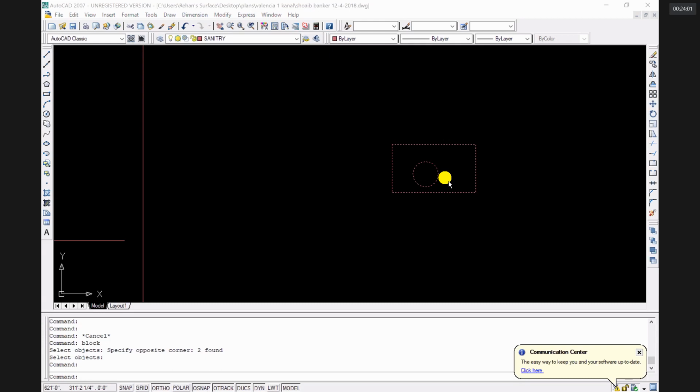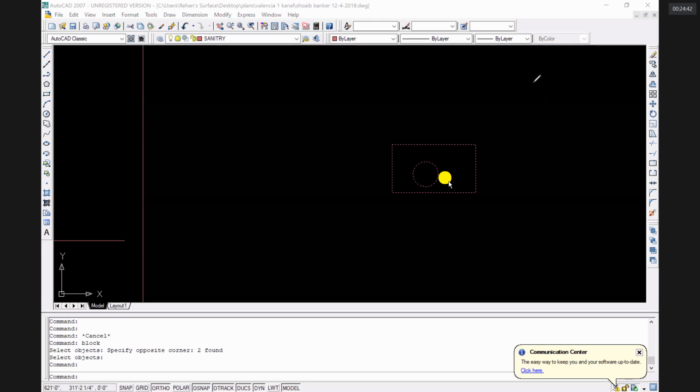Now, if any foundation is constructed at the property limit, your foundation cannot go outside that line. So what is done in that case? Unsymmetrical or asymmetrical foundations are provided. It means whatever steps you are extending on both sides would be extended on one side only. I can share a sample of an unsymmetrical foundation with you, but I would also draw it over here.